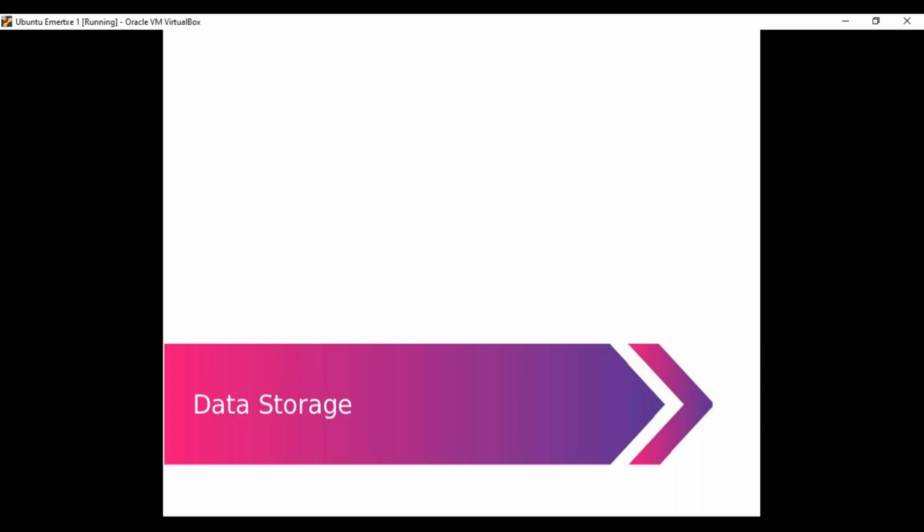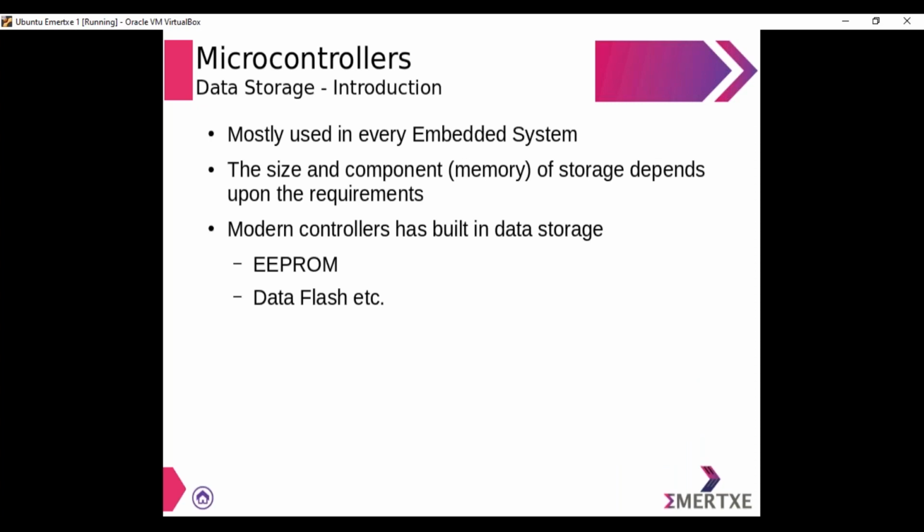And the disadvantage is you will have more write cycles. I mean, to have a small amount of data written, you will need much time. Okay, so that's the disadvantage of an EEPROM. So the writing speed in case of EEPROM is slow, it will take more time to write a small amount of data. But let me tell you, in our case, our microcontroller comes with a built-in flash memory. It also has an EEPROM.